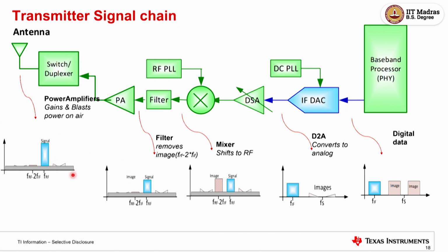Now you see what all you have got here. You have got some information which came from the image, which got filtered by the DAC. You got something from here, because if you are mixing, you filtered. But these are the residual that you have created. But you are supposed to be ideally sending only this. So you have transformed the information from IF into your carrier frequency. This is what is going in air. But these are the other things that you have created. Now we will see what are all the impairments or the effects of this.